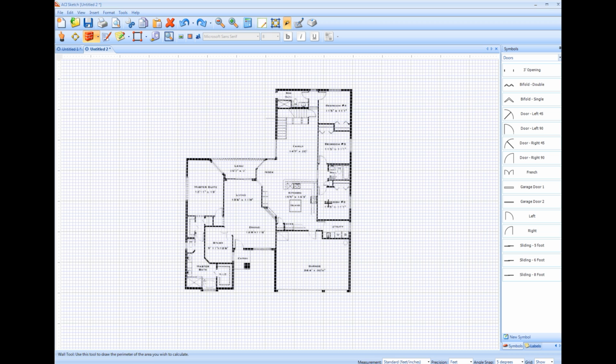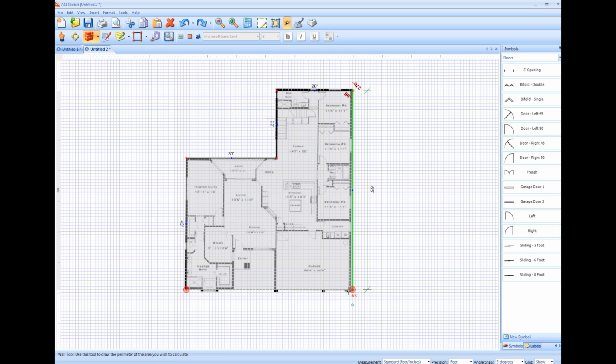In the upper left-hand corner, I am on wall mode, so I'm just going to draw a quick sketch over top of this existing image. You'll notice, especially on the wall that I'm currently at, this scan was not created evenly. It's skewed a little to the right, so that won't exactly line up, but that's okay because, as you know from earlier on in the training, ACI Sketch allows you to easily manipulate the floor plan after the fact, so I can make these small one foot or half foot adjustments fairly easily and quickly.